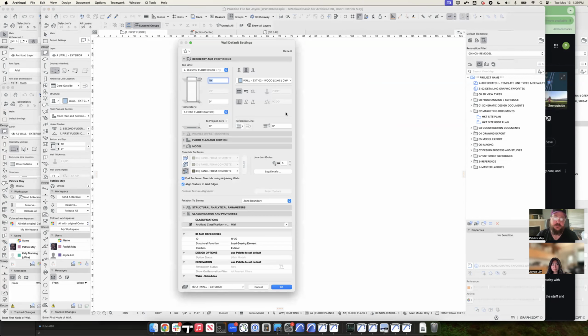That said, obviously for things like maybe half walls, screen walls, railings, stuff like that, we might not want the wall to be linked to the floor height. But otherwise, that's fine. And it's actually preferred for most walls. Now, this is the vertical dimension where it sits relative to project zero, to its home story, its total height, relationship to the story is all controlled here.